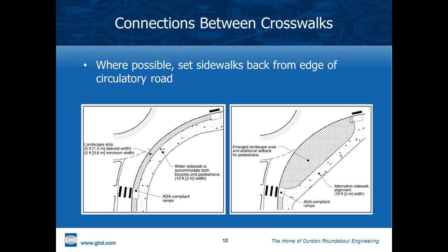And this sort of enclave-looking area could be planted, could be landscaped, it could be a combination of contrasting brick pavers and some landscaping treatment, as long as the height of it doesn't restrict sight to the left from drivers entering downstream.